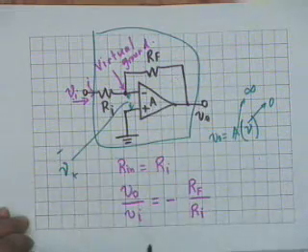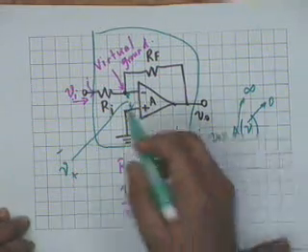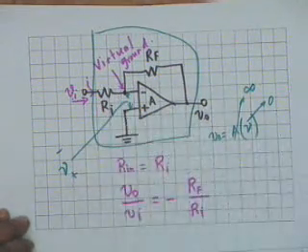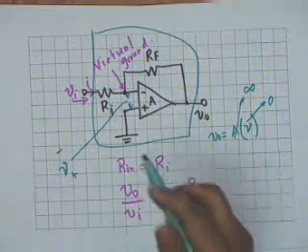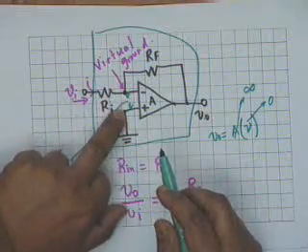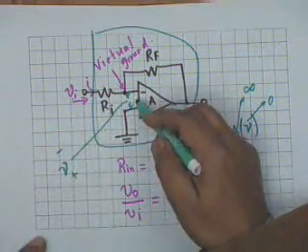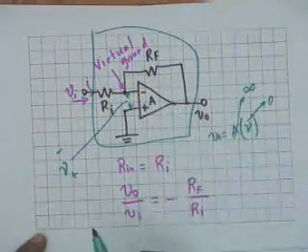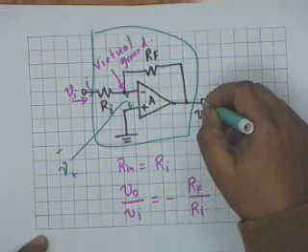So what will happen if in the inverting configuration we don't have an external resistance? We don't have Ri. Then the gain shall be infinite. If Ri is not there, Vi is applied directly at the input terminals of the op-amp, which means that it is multiplied by A, which goes to infinity, and your V0 shall go to infinity.